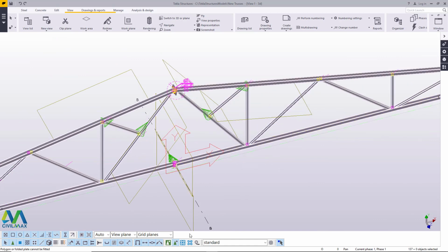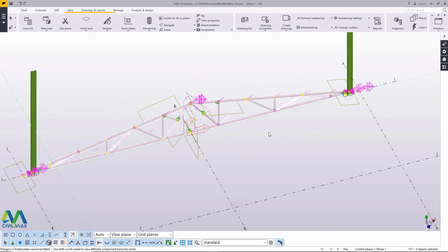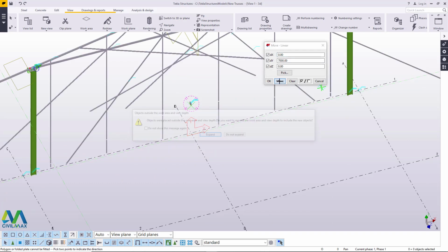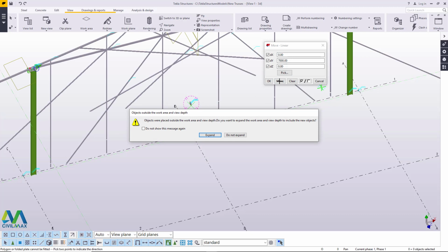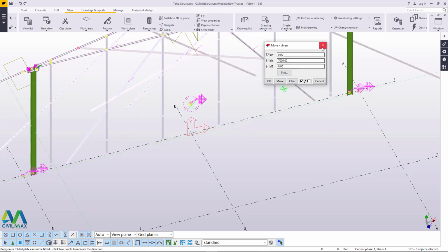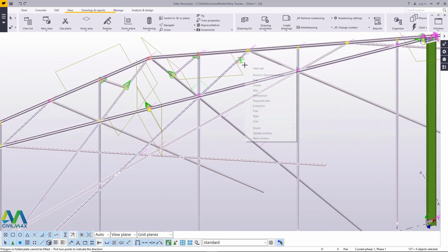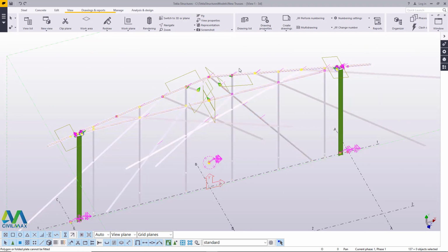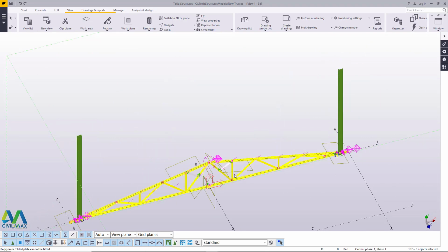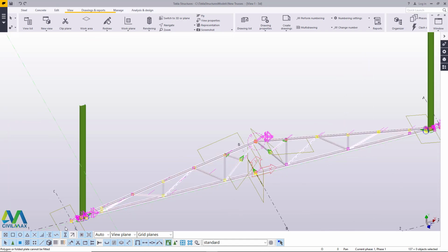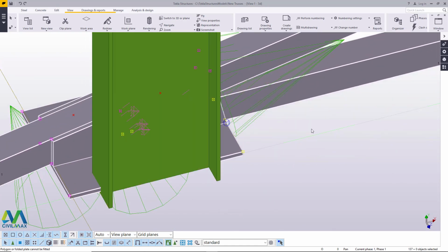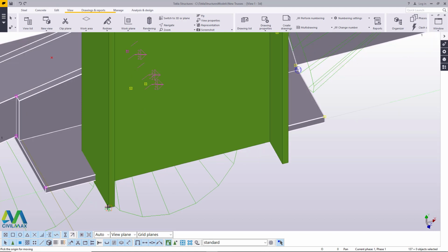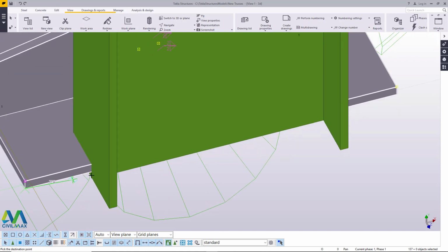And what we'll do, we'll first of all enable the assembly, and now come to move and click linear and try and move it up. It's still clashing, so a problem now is we should have worked it up here, up the column, and we'll undo that. So what we'll do, we'll just pick it at the bottom end here, right click and come move, and pick it right at the bottom end here,